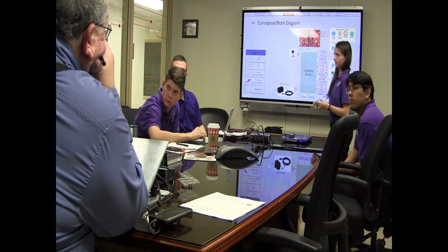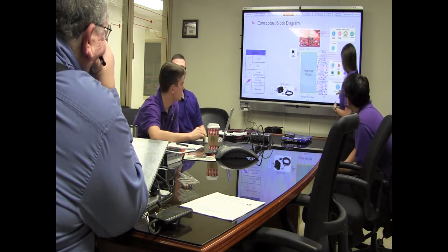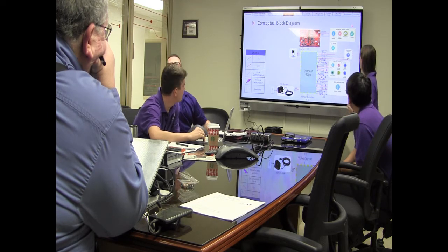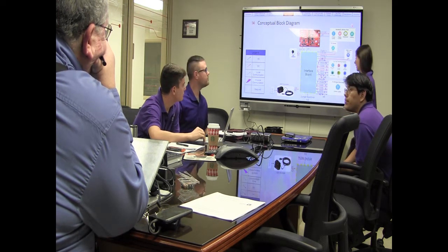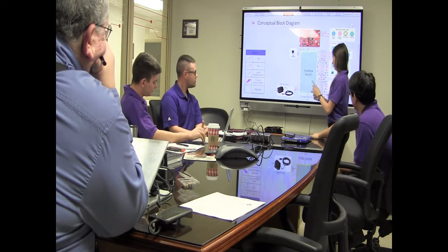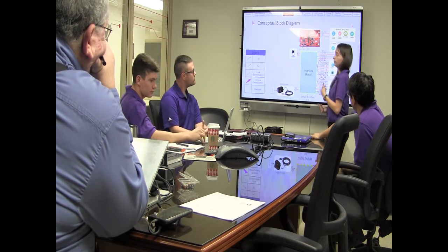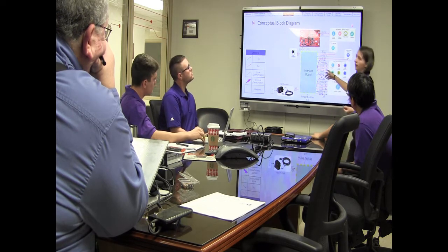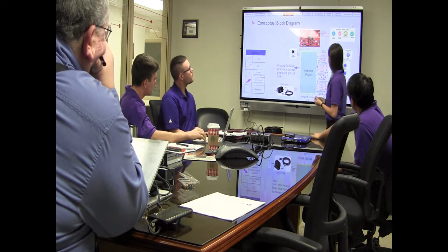Okay, did you say stepper motors? No, that says control lights. No, up on the other one. She said servo motors. Servo motors. Okay. Yeah. We also have, for each port, a jumper switch, a little bar switch that'll let us control 5 volts or 12 volts that we're sending out on our voltage lines.